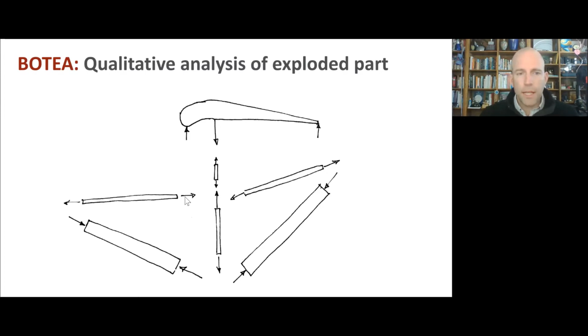These are kind of pulling against each other, and these are kind of pulling against each other. So that results in a structure where the center pieces are pretty mass efficient, and then we've concentrated our buckling resistance and bending resistance into bending into this, and then buckling into those bottom elements.